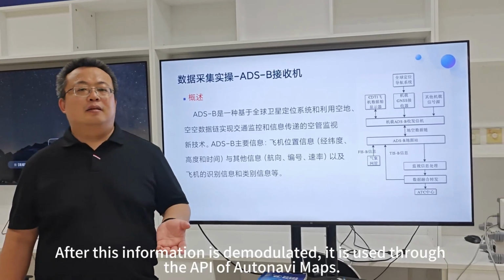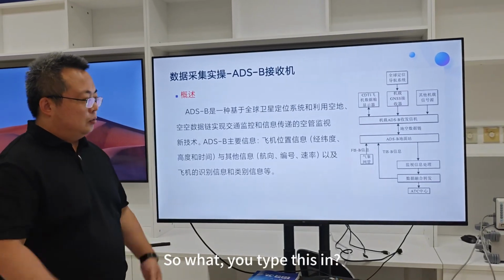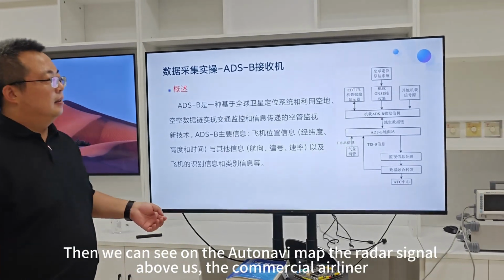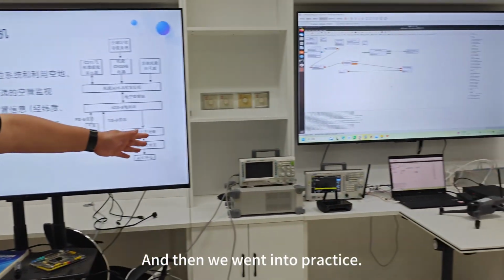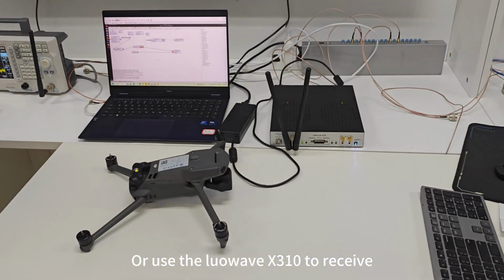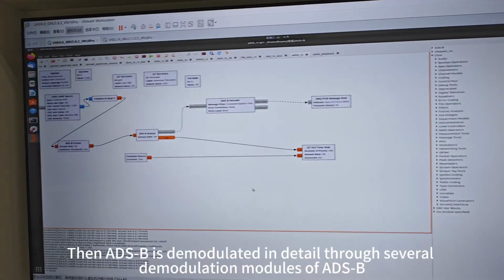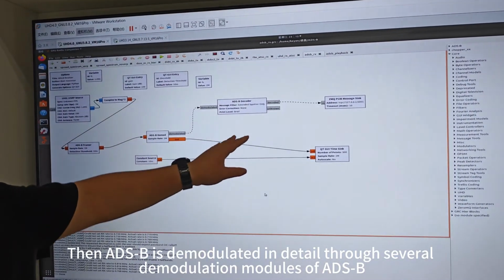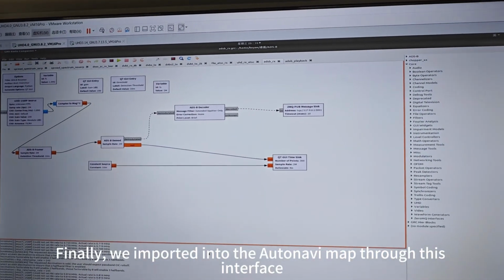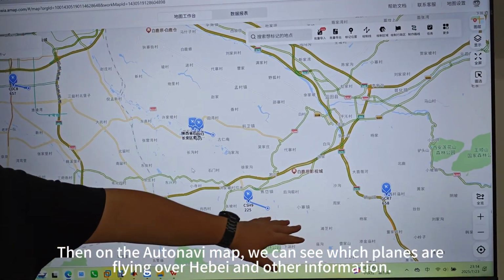After this information is demodulated, it is fed through the API of AutoNavi Maps. Then we can see on the AutoNavi map the commercial airliners above us, like a radar display. And then we went into practice. Same thing, we use the USRP X310 to receive. Then ADS-B is demodulated in detail through several ADS-B demodulation modules. Finally, we import it into the AutoNavi map through this interface. Then on the map, we can see which planes are flying over Hebei and other information.